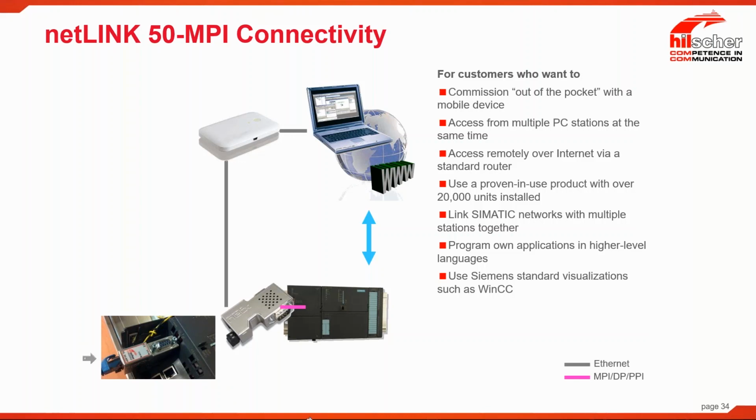And then at that point, this is a TCP/IP output, and you can literally then network that controller to wherever you want. You put it on your local network, and at that point you have access to it back even to a control room. So all the programming, all the maintenance that you would normally do locally, you can do that. This is also very easily used by service people. They keep the connector and a length of Ethernet cable in their bag, and they're able to do a lot of their programming from a more comfortable position than just standing in front of that controller.